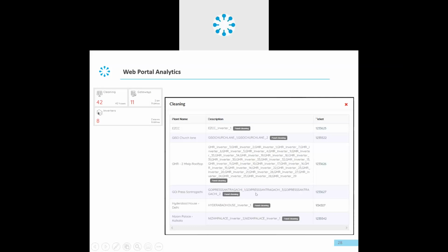So generally it raises an alert of cleaning based on the inverter levels or the strings connected, depending on the degradation of the performance from that inverter. This is not a sudden generation. This generation usually occurs after 2 to 3 days of gradual performance degradation, because initially it checks several other concerns of degradation. If it doesn't find any further issues, but the performance is still degrading, it raises an alert to check the dust accumulation.